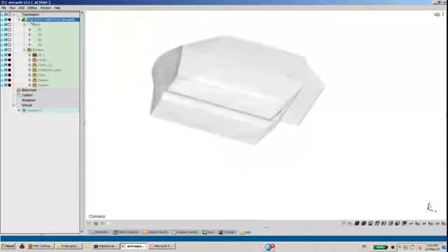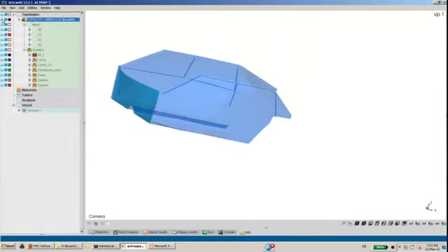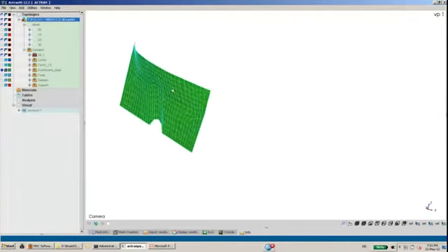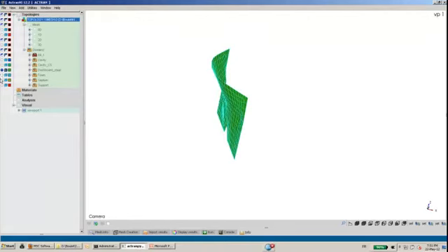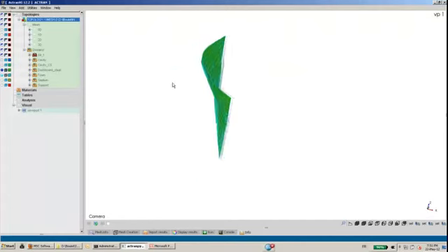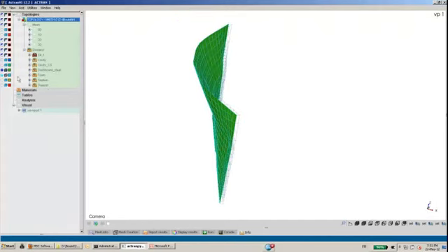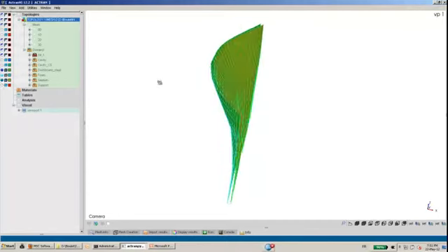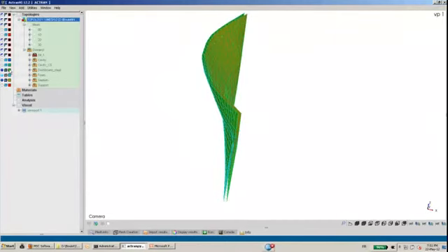The first thing I'm going to do is change the colors of all that and try to identify the different parts of this mesh. First of all, I have the dashboard here that is made of 2D elements. Then connected to this dashboard, I have the 3D elements for the porous material. And then connected on the other side of the porous elements, I have a domain made of 2D elements again, that is the septum, the heavy layer. So that's for the structure.